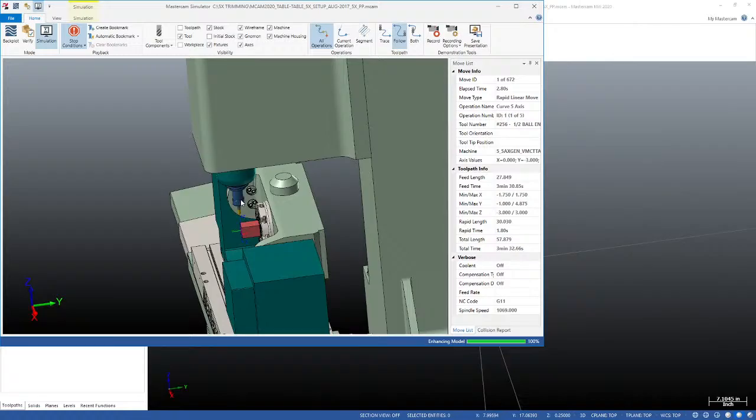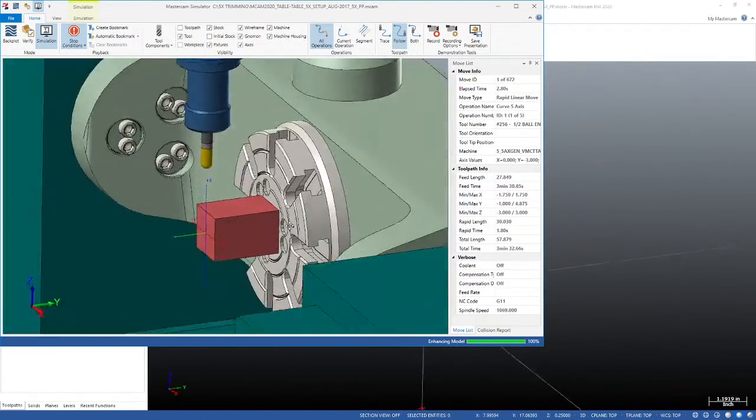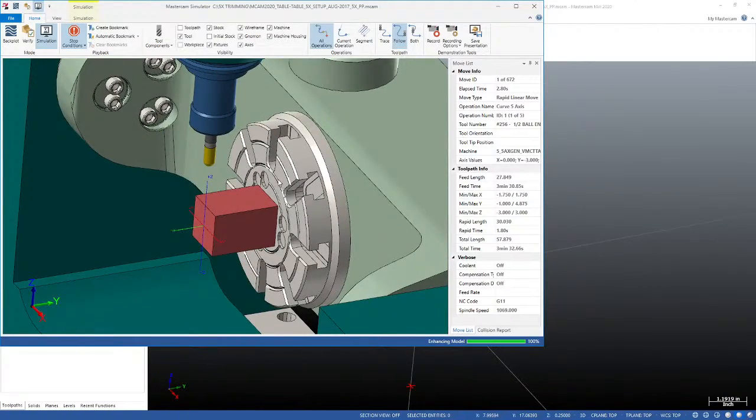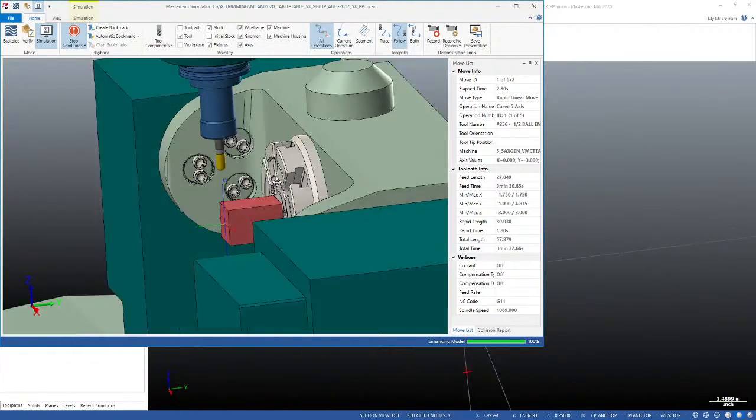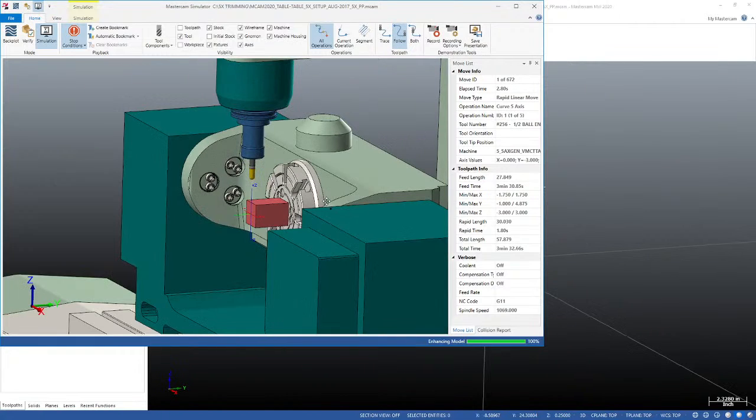And so by default, Mastercam is going to put the bottom of my stock, or whatever's visible on the screen, aligned to the platter or the rotary, or the 0 point of my machine, basically. So sometimes what we want to do is load our workpiece with some simple toolpaths to check clearances, and use that to inform our fixture design. How far do we want our fixture to stick out?